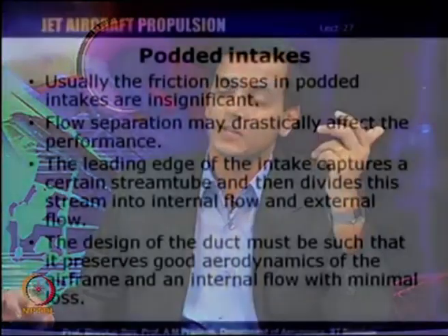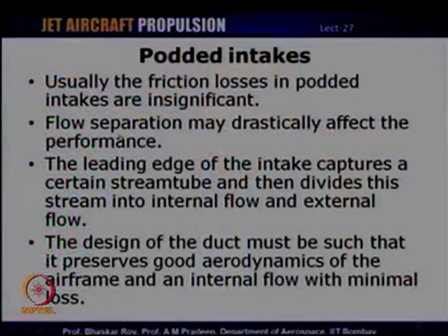And therefore, in the case of podded intakes, the presence of separation of course will affect the performance of all types of intakes, but if there is a separation within the surface of the podded intake, then it will drastically affect the performance.